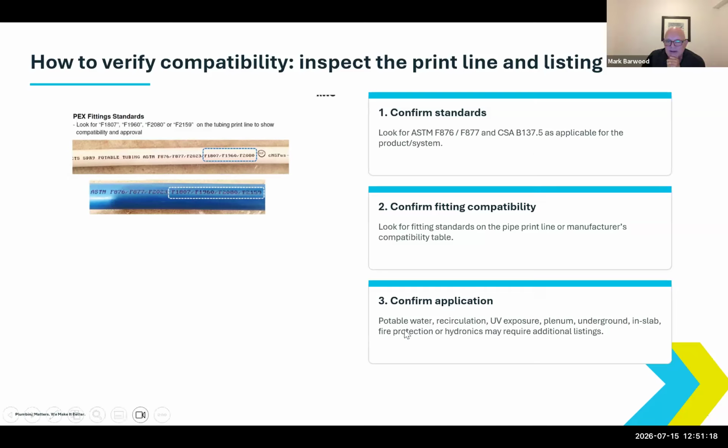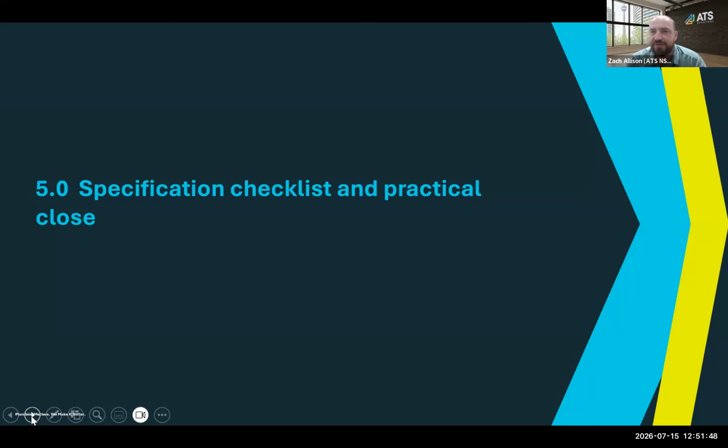So just before we finish up here, because we've got about 10 minutes left, we had a great question come in that I really want to hammer home. I think of the certifications that you were just going over, looking for hot water recirc applications, and understanding how the PEX tubing degrades, or how it fails, and specifically whether chlorine exposure, temperature, and other factors lead to brittleness, the bursts that we've seen in some of the videos that go around online, micro cracks, pinholes.